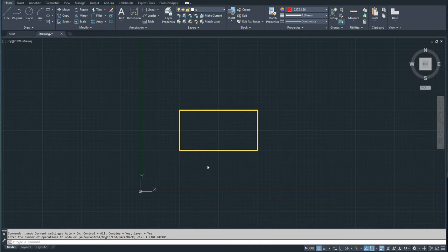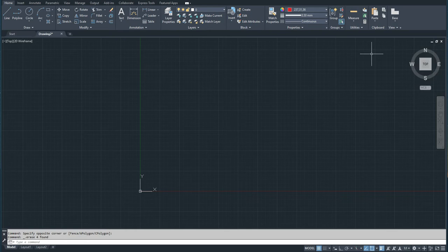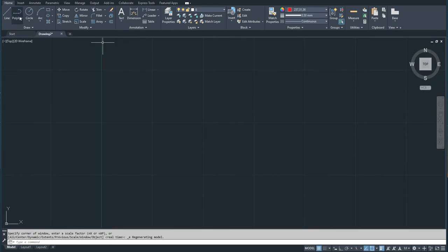Now, how can we draw a line with certain length and angle? I will delete everything. So let me choose everything like this, from here to here, click and click, then delete, zoom, extend, draw a line. I will choose a line start point anywhere here, guys. AutoCAD now asks me to enter the next point. I will move the mouse. From this point, I will write at.